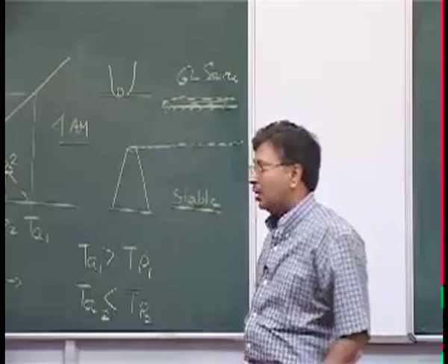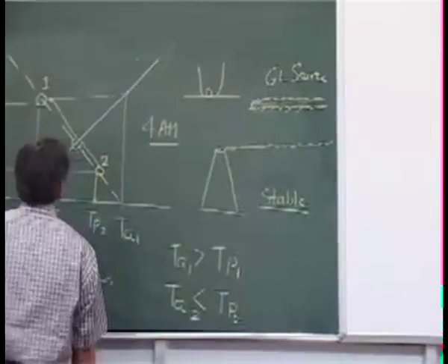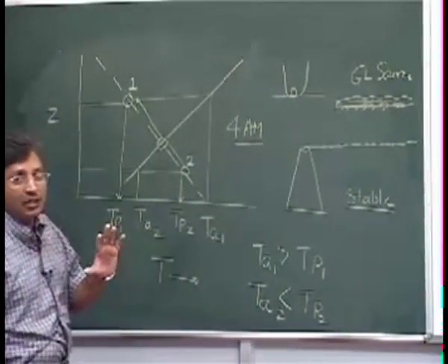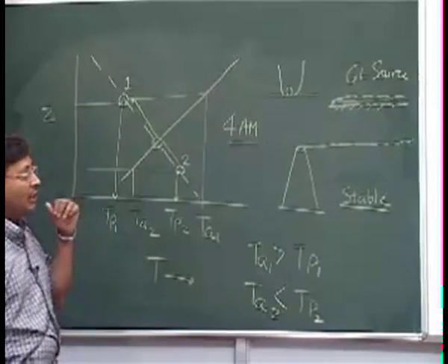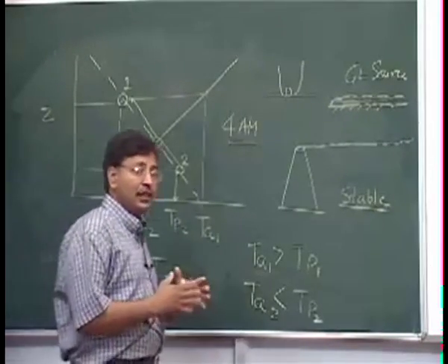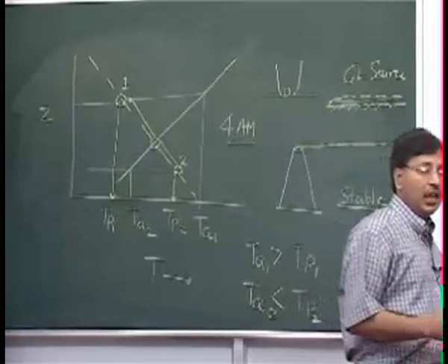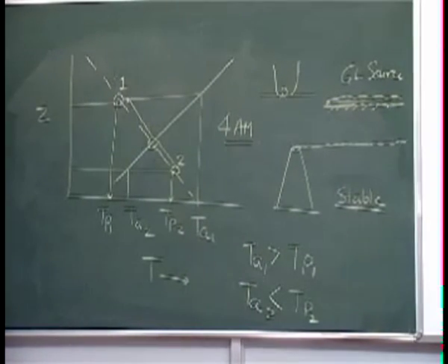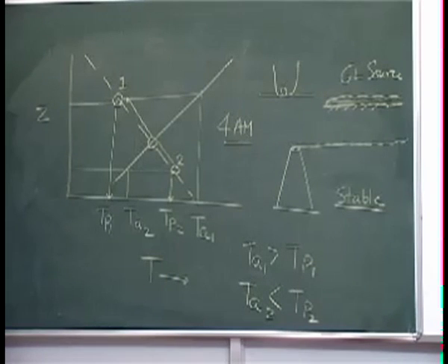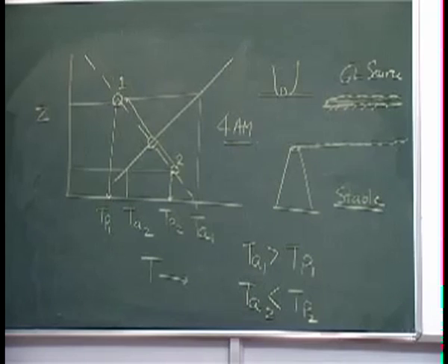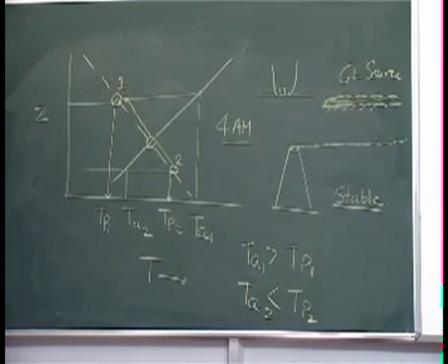So you see here, what we have done in this lecture is that we started with the atmospheric stability, and said that stability varies depending on the time of the day, and that concept of stability, we took from the atmospheric stability to what impact it will have on the particles or the pollutants, and how the pollutants can behave. That is what we tried to do so far. Important things, and somehow or other we will utilize this.